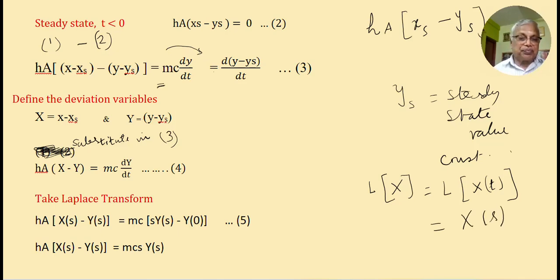Similarly, Laplace transform of y becomes y of s. And this is the first order differential, mc into dy by dt. The transform of this is mc into s into y of s minus y0. So this equation 5 is the Laplace transform of the first order differential equation.